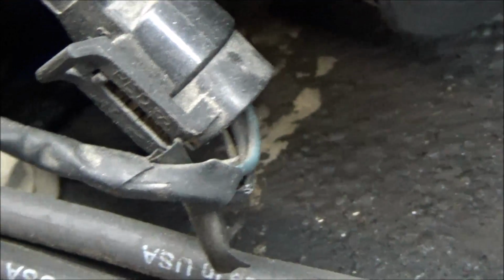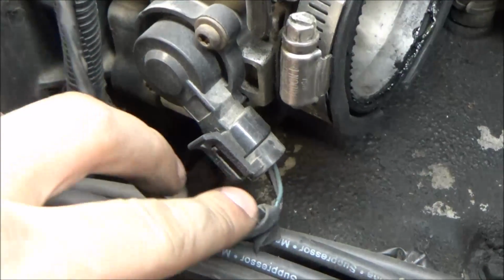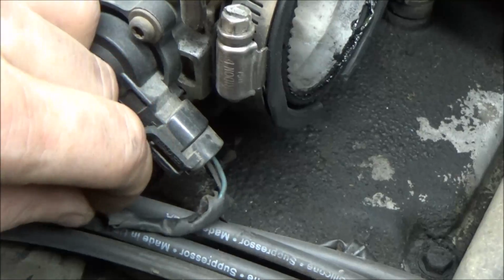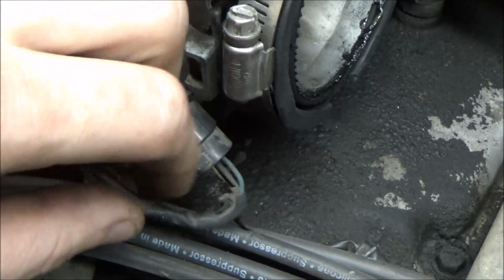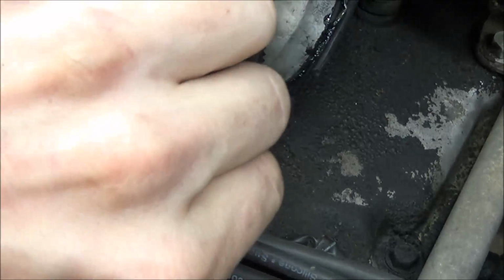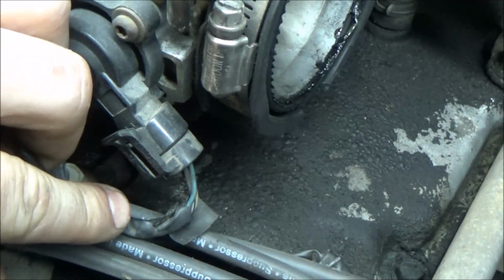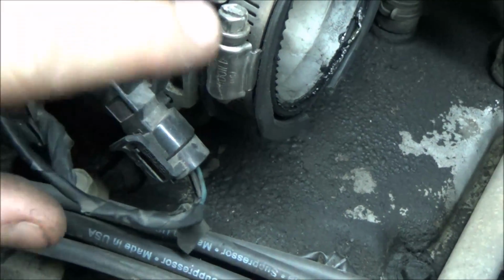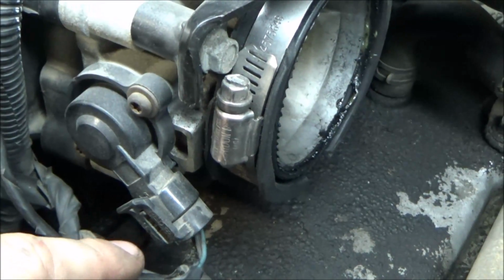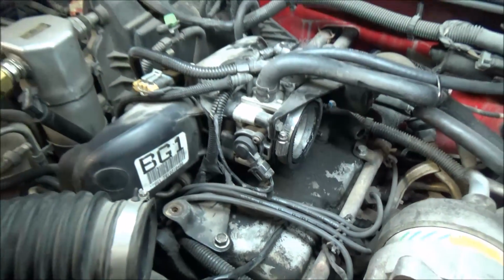So as we can see, this is a 3-wire potentiometer here, guys. We have 3 wires coming off of it. I have what appears to be a gray, maybe. I also have a blue and what appears to be a black. Knowing GMs of this vintage, the gray wire is going to be the 5-volt reference. So there's some good information for you guys. But all we're going to do at this point, guys, is I'm going to get the Vantage. We're going to start testing these circuits independently, verify we have good circuits, and we'll see what's wrong with this thing.